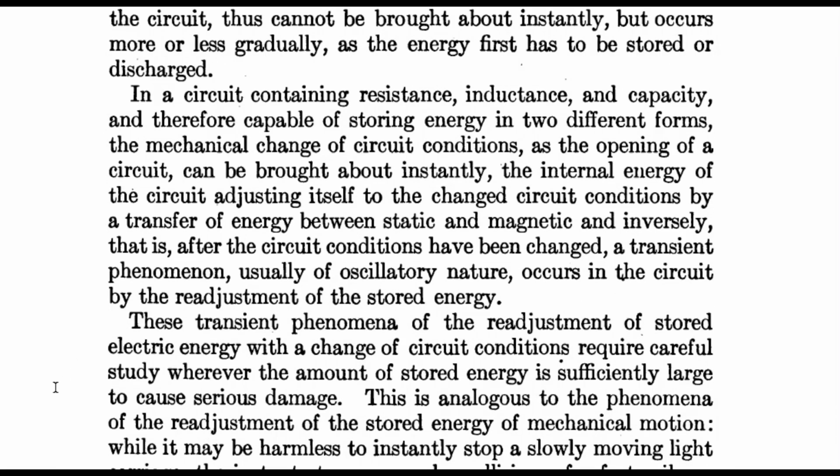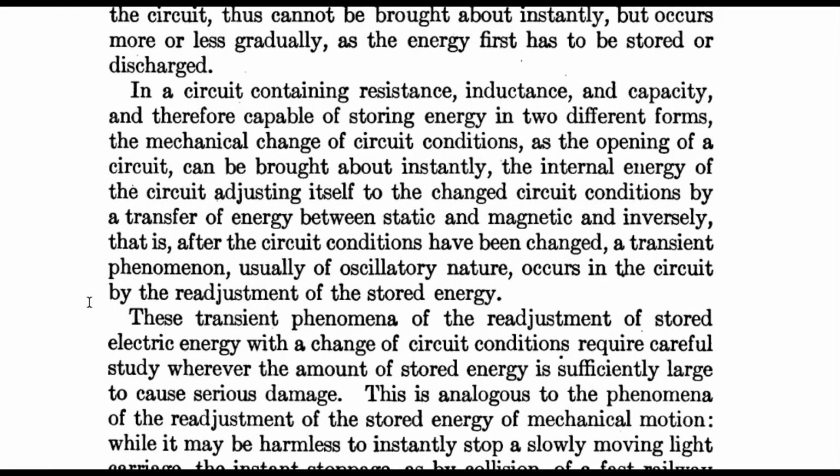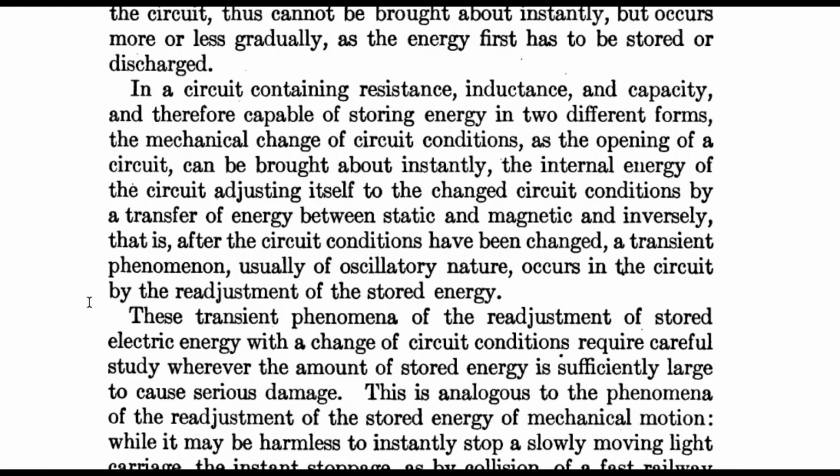In a circuit containing resistance, inductance, and capacity, capable of storing energy in two different forms, the mechanical change of circuit conditions, such as opening the circuit, can occur instantly. In this scenario, the internal energy of the circuit adjusts to the changed conditions through a transfer of energy between the static and magnetic forms, and vice versa. After the change in circuit conditions, a transient phenomenon, often oscillatory in nature, occurs as the stored energy readjusts.